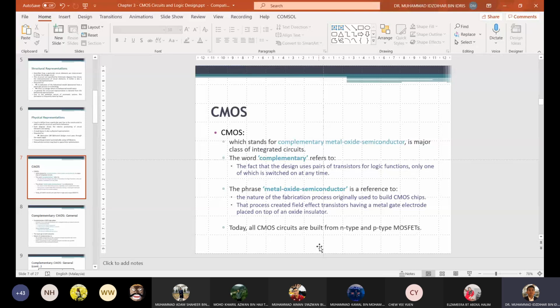There are reasons. If you Google, you can find it, but it's whether you understand or not. If you use CMOS, the good thing is you complement. To conclude simply, it saves more current. The consumption current and leakage current are lower, because you only use it when you turn it on and when you don't use it, you turn it off. So leakage current is very low. So you can have low power consumption devices. That's very good.